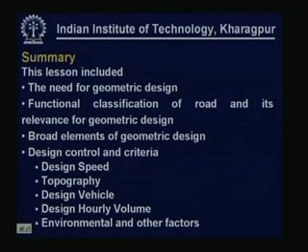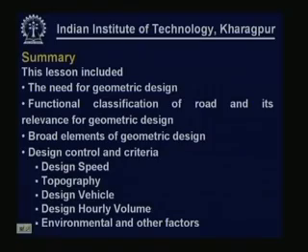Under this design control, the need for terrain classification, the mixed traffic condition, a way out to express heterogeneous traffic stream into a stream of homogeneous traffic by using passenger car equivalency value, and we have also talked about the ADT, what we normally measure in the field, how to convert ADT to AADT, annual average daily traffic, then how to estimate design hourly volume from the AADT.